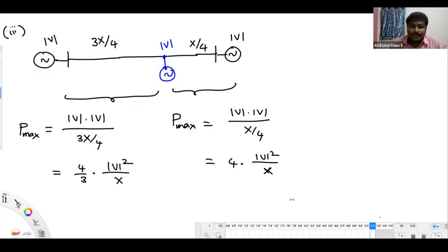Very simple thing. For example, if you are keeping loading based on the second value, which is a very high value, whatever the power flow you are deciding may be higher than this first number, right? Then the system will lose the synchronism. That's the issue.